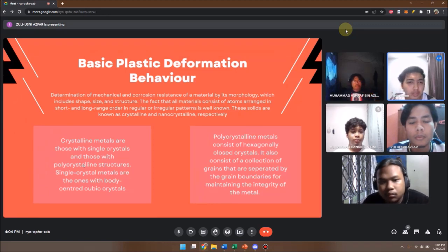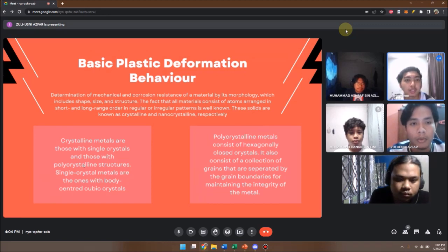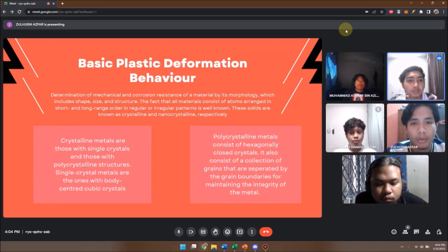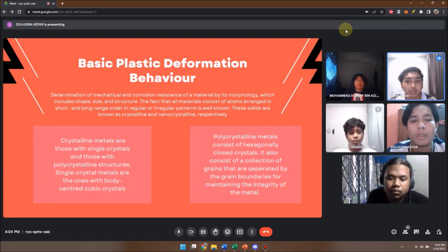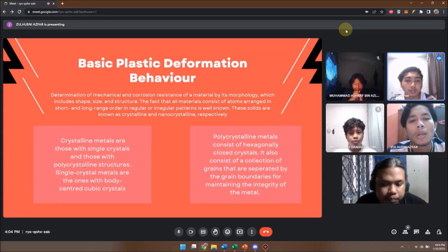Now I will talk about the process of recrystallization. First, the work hardening. The process of work hardening is also known as strain hardening. During this process, dislocation density is increased under the recrystallization temperature of the metal so that it becomes stronger and harder. There will be a pinning effect between dislocations. This highly flawed microstructure will also prevent crack propagation as a result. The probability of rearrangement of metal and dislocations increases with increased temperature, resulting in lower strength and increased ductility.